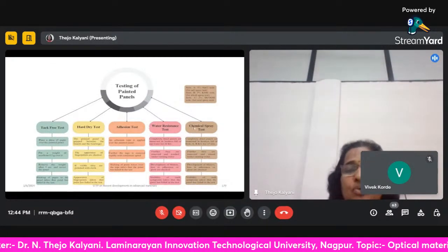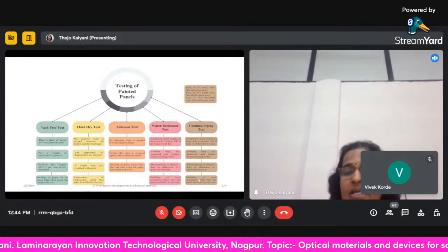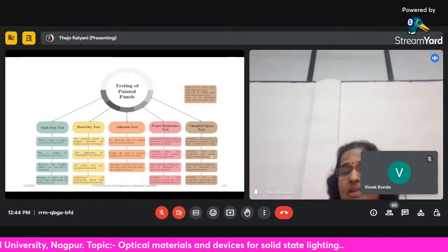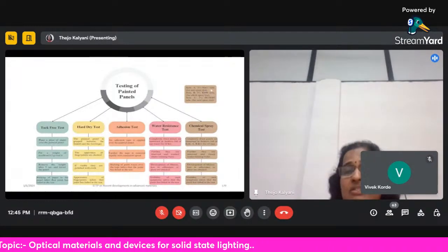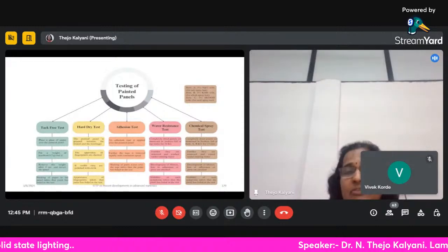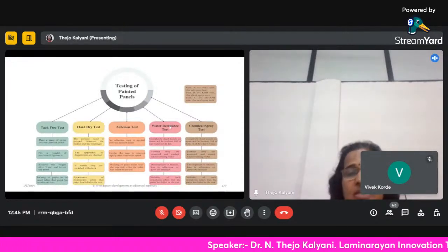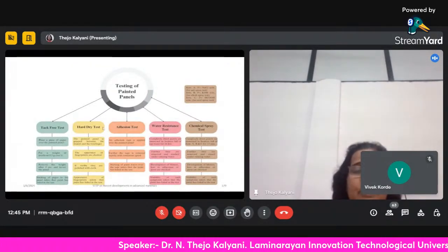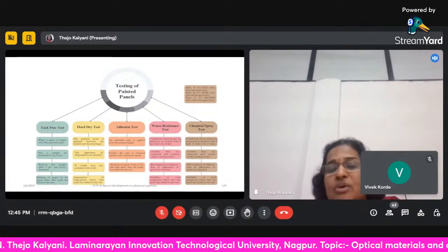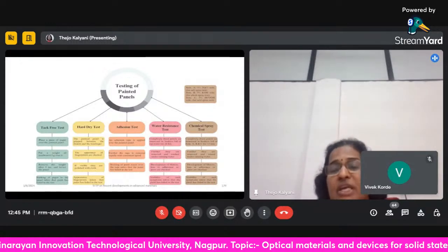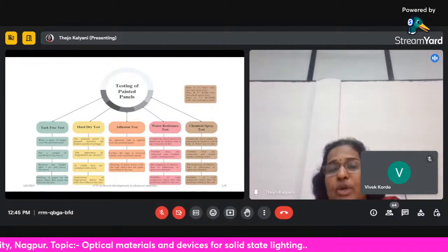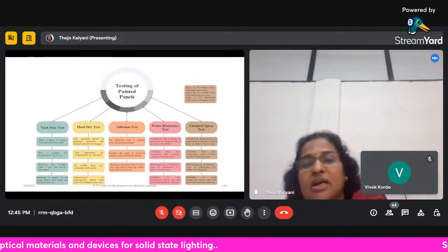And in a few cases, we failed. In this particular chemical spray only, with NaCl, whenever it is sprayed onto that, we have observed that dark spots have developed. Otherwise, it's water resistant. In the adhesive test also it has passed. In the hard dry test also it has passed. In the tack-free test also it has passed. So we need to work on that chemical spray test, and we need to come up with a solution about which chemicals are going to be friendly with that particular combination.